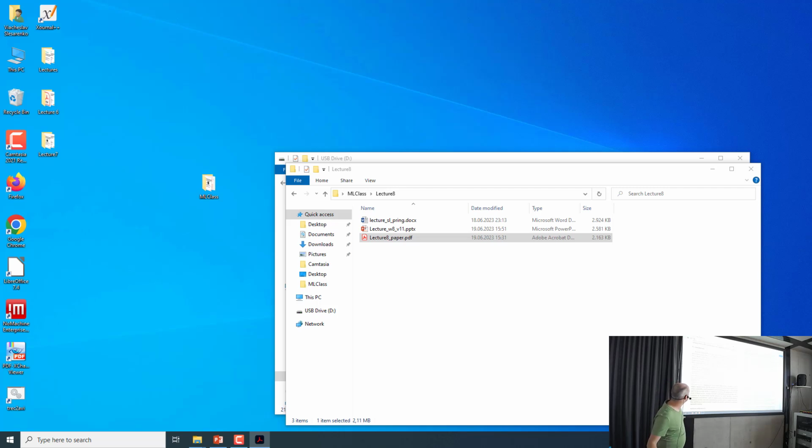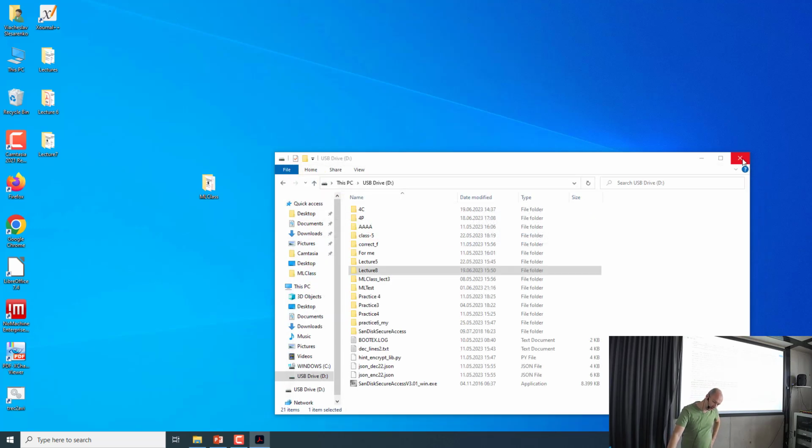But I think the important thing is that when they comment on the comparison of the predicted degradation curves with the real degradation curves, it is noted that the predicted curves have larger errors when the prediction is made using data from the early stage of flight cycles. So if you don't have enough data, they actually fail to predict. You need to have enough data, especially data that goes a little bit down, in order to nicely train this recurrent model that will be able to predict the remaining lifetime of your engine.